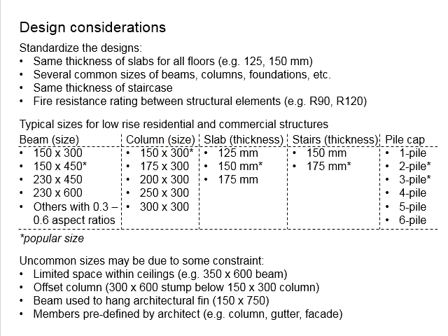This will make the columns rather slender in one axis, which 150 times 300 already is. You have to be careful with the bending moment. In terms of the axial capacity, increasing this 300 to 350 or 400 in fact does not significantly increase the axial capacity, but you may have concern with the lateral buckling or the slenderness on the smaller axis. You should design the column carefully.